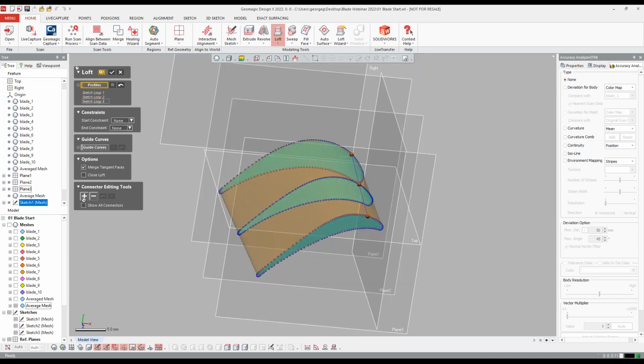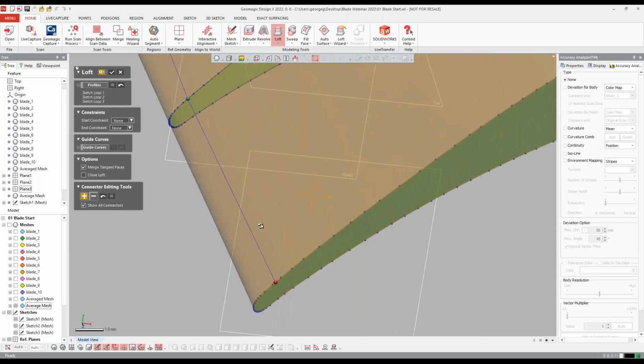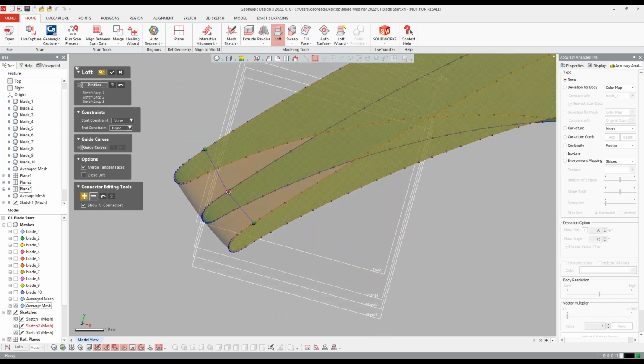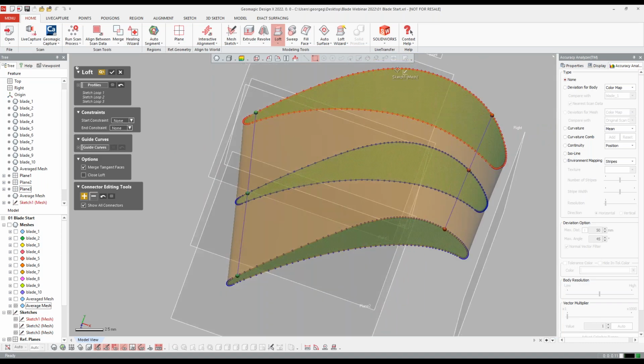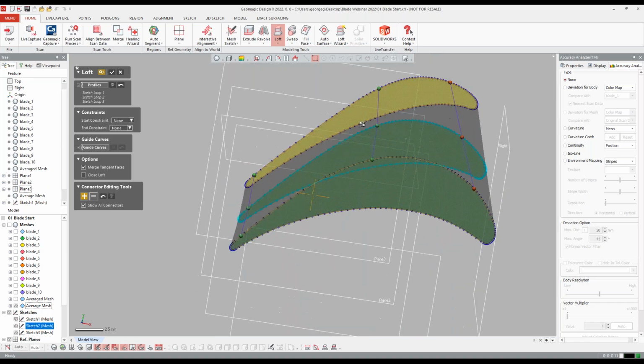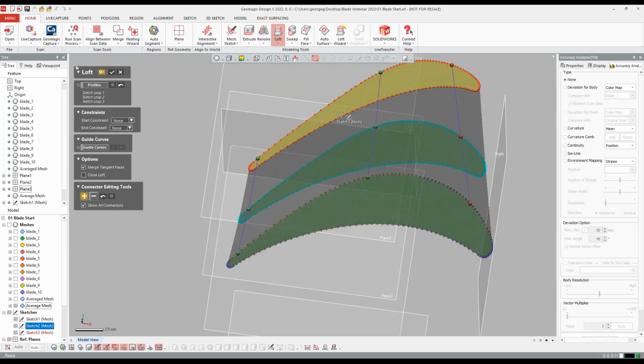But now we added this ability to add connectors here. So if I just click and create extra connectors, and then I can drag them and manipulate them. So you can add a bunch of them here. So I just added one there. You'll see here, so you can create much better geometry to start out with, right? By adding these connectors and aligning them in this way.